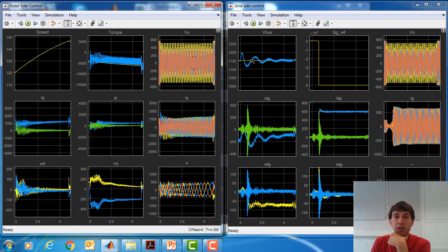There is a perturbation at the DC boost voltage, but the current loops for negative and positive D components, negative and positive Q components work properly. As we have seen before, there are some oscillations just at the beginning of the voltage dip, and this is due to the oscillations that go through the notch filter that we have used.